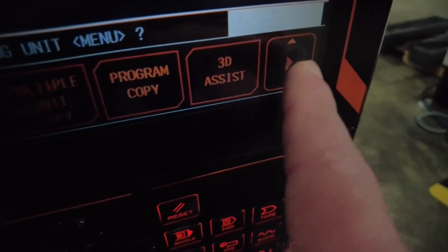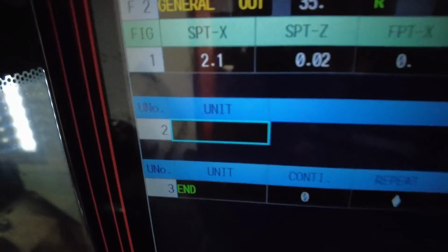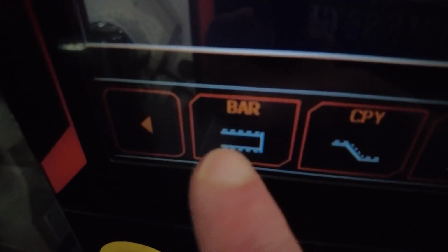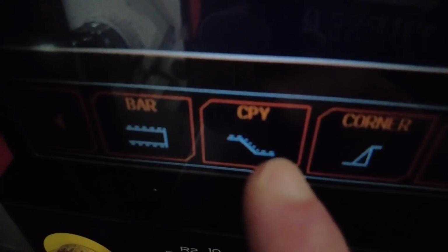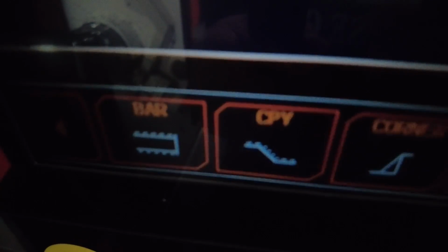Okay, so go over here, right key, insert, press OK. So unit, highlight it, go to turning, same thing. Let's go through all the options. OD turning, it's gonna say bar out. Copy. What copy is, it's something similar to OD turning, but instead of turning when it goes, let's say from the face throughout the part, this actually copies the shape.